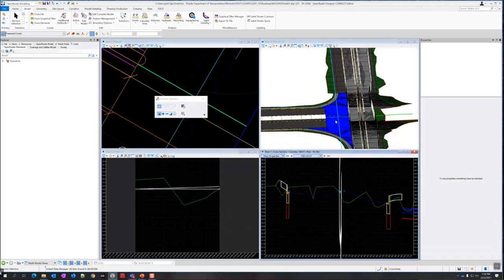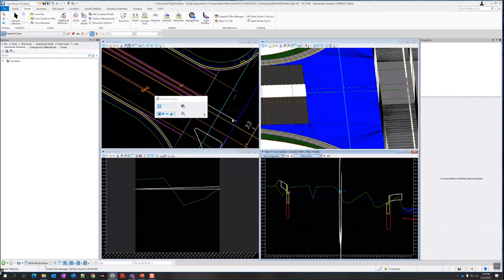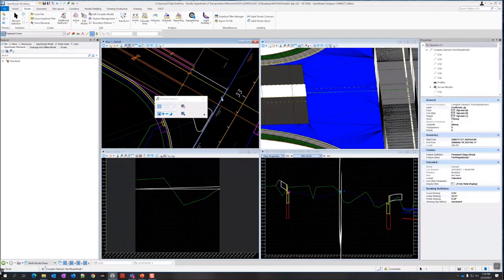And you may also do these for the other lines. It might also be useful. Maybe that's why I have this large break. Maybe if I had a tighter stroking definition on this line here, that would work better. So I could select pavement break, go to linear stroking and change that to 5 feet too.